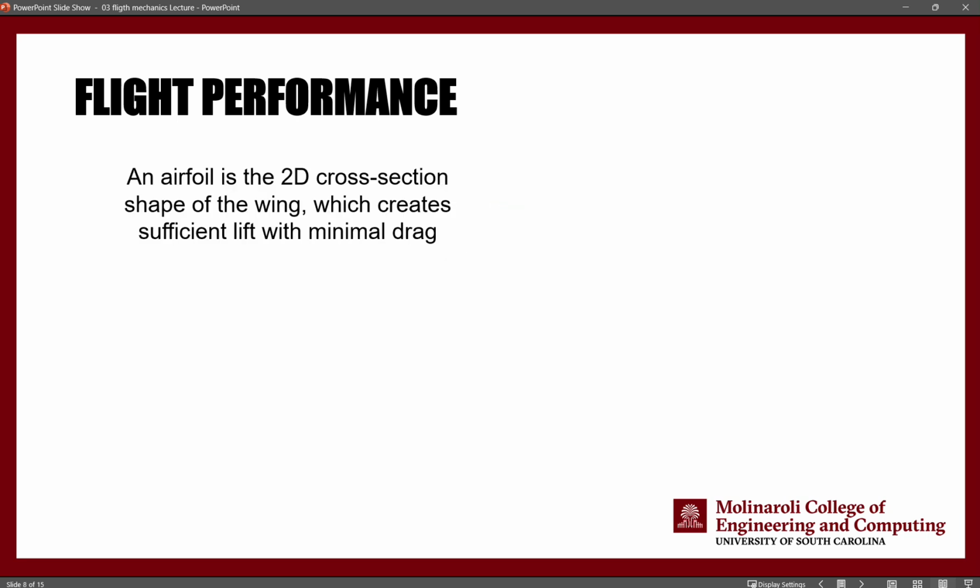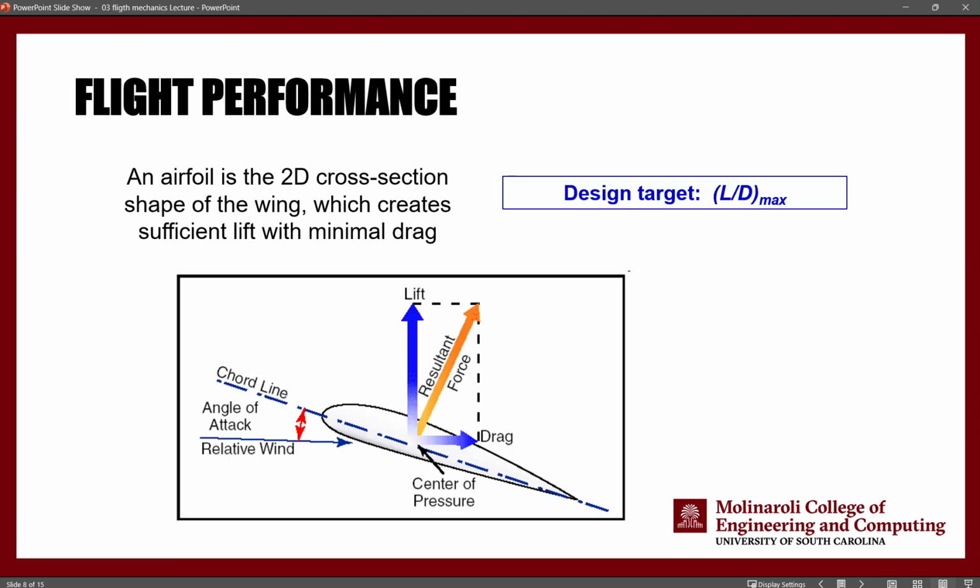Okay. So before talking about the angle of attack, we have to talk about airfoil. An airfoil is a two-dimensional cross-section of the wing. Very simple. Essentially, when you cut a wing, the cross-section of it is going to look like a teardrop shape, an airfoil. And this airfoil can have a high curvature or low curvature. The curvature of an airfoil is called the camber of the airfoil.